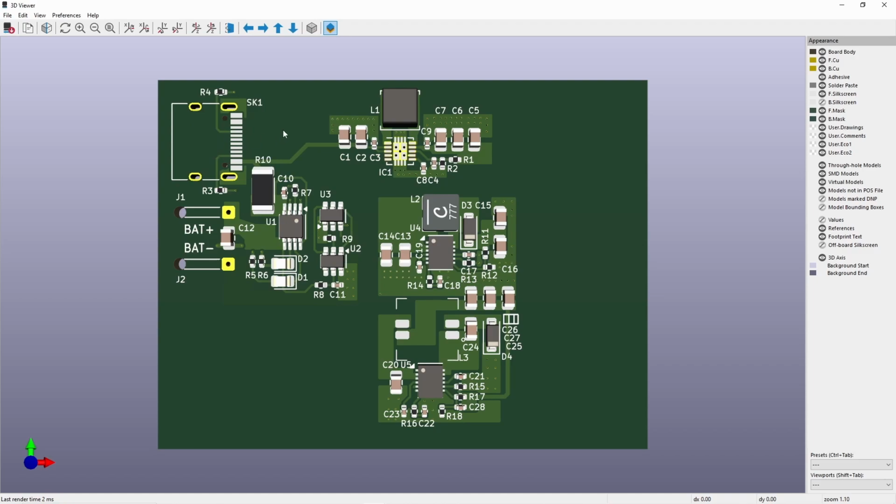This, I want to basically have 5 volts going to these two ports. And I will add a switch that can select either the supply from here or directly from the USB. So obviously this part will be used when we have 4 AA cells or the rechargeable battery. So I think I will need to move this down here and I'll move the USB-C connector down here somewhere.